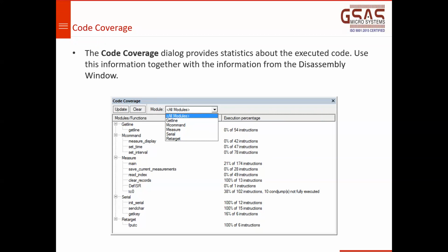The trace I'm talking about here is instruction trace. It needs the JTAG debugger which you connect to your hardware, because real-time trace is not possible in simulation. The debugger should have the intelligence to understand the data coming to that instruction trace port, which we call the ETM port or trace port. What instruction trace does is capture all the opcodes the processor has executed and send them to the ETM port, and the debugger, which is capable of understanding this information, captures it and shows it in the IDE.